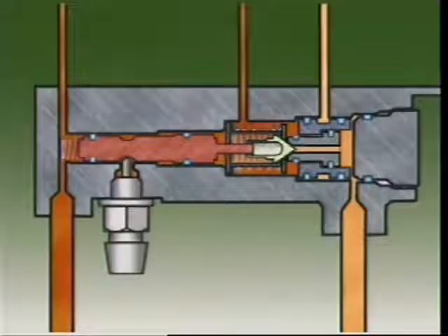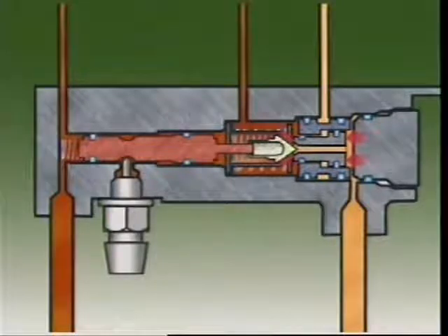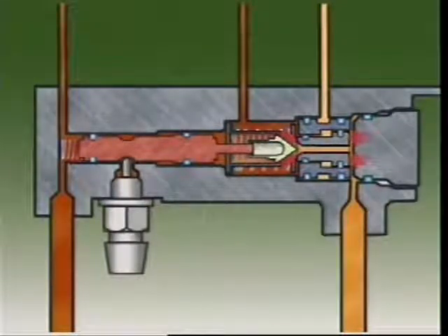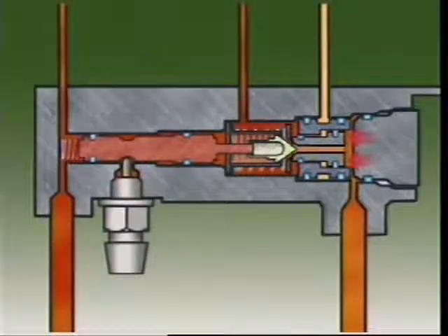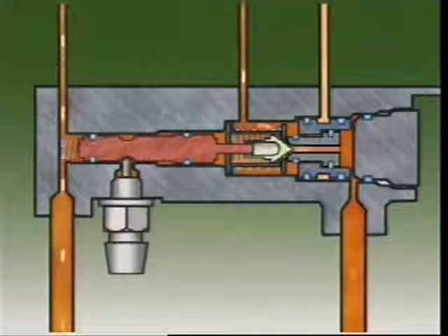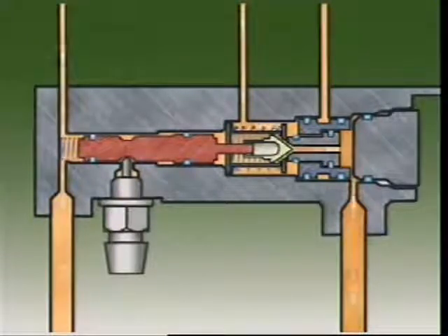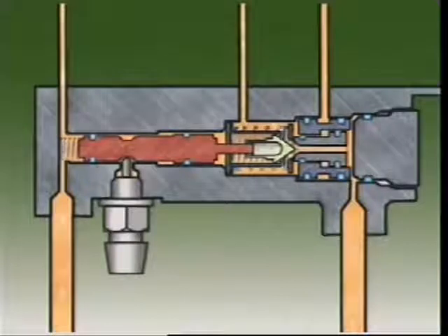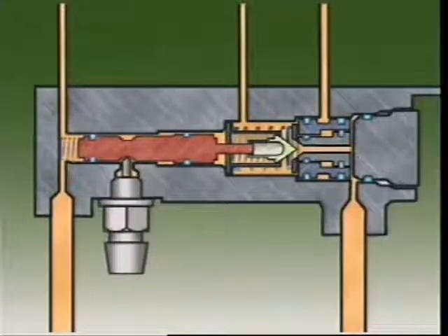As greater pedal force increases pressure in the master cylinder, fluid pressure rises on the smaller end of the piston. This combines with the force of the pressure spring to overcome the lower pressure now on the larger end. This forces the piston back, clear of the poppet valve. The increased pressure now acts on the larger end of the poppet piston and again forces the piston forward to contact the valve. When the pedal is released, the pressure of the rear brake fluid unseats the poppet valve, letting fluid return to the master cylinder. The pressure spring now returns the poppet piston to its relaxed position.